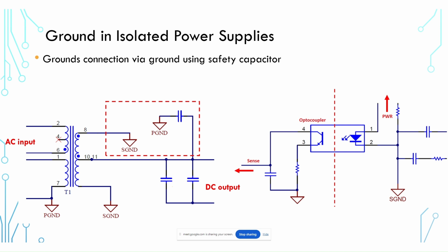And if you're not sure what a Y-type capacitor is or how to find one, just go onto a component search engine, go onto Find Chips or go onto Octopart and search for Y-type capacitor or Class Y capacitor. That would then give you some results that will show some capacitors. You can read all about what their ratings are and what some typical components are.